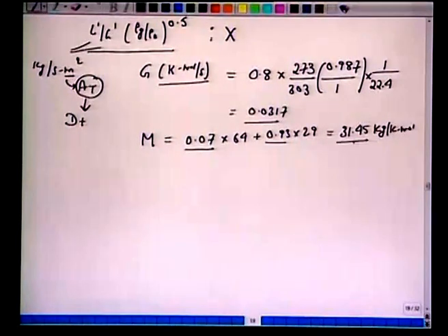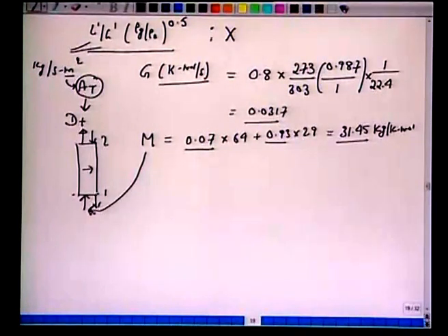Now, it is also important that we understand that in this column the mass flow rate of the gas will change as the sulfur dioxide is stripped, it was absorbed in water or on the solvent. Essentially, we have 1 here and we have 2, and molecular weight we have calculated. I was trying to point out here that this is based on these G1 conditions. Why? Because at one end we have very high flow rates. So, liquid which also trickles from this, it is enriched with sulfur dioxide. So, one does the calculation based on end 1 rather than based on 2. So, we have calculated this based on this 7% of sulfur dioxide which is in this gas phase here.